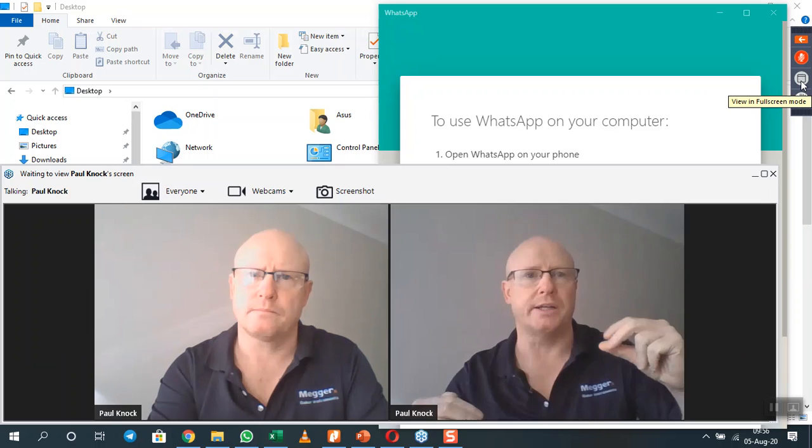I think the question is born from some of our competitive testers that don't use this high voltage to identify that early insulation that can be spotted during the startup and stop. Because what happens is during that startup and stop of the motor, if there is weak insulation, you're going to get arcing inside.